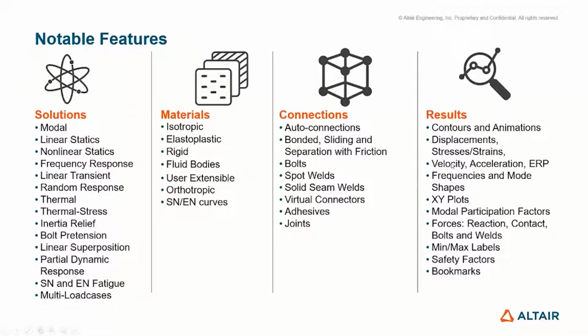Now, these are just some of the known features in SimSolid that we're looking at. So like we said, you can look at statics as well as dynamics in SimSolid. Now, you can look at a modal analysis, and after the modal analysis, obviously you can take it through for a frequency response or random response as well. But then if you want to look at a structural, you have your linear and the nonlinear side. You can look at thermal and any other sort of nonlinear phenomenons like inertial relief or bolt pretension. You can include all of those in. And last but not least, you can also start looking into fatigue as well in SimSolid.